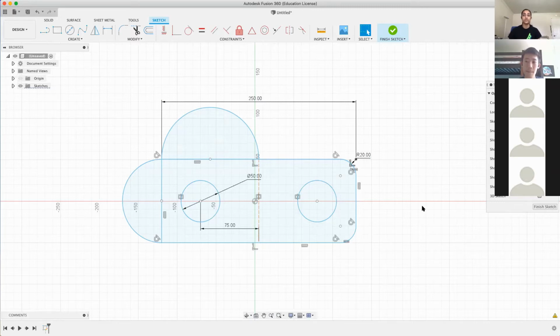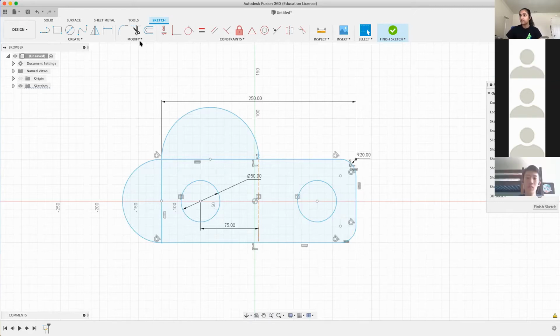This might seem like something you can't avoid, but it's really important to either file down your metal or to create these kind of rounded edges, because it is a huge safety hazard to have sharp metal on your robot. And so this is where a lot of teams will use this fillet feature here and into the 3D section because they want to avoid even having to manufacture these sharp edges. So that's a fillet tool.